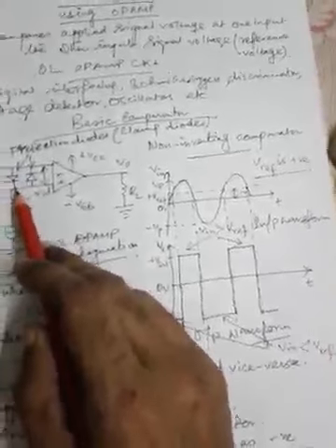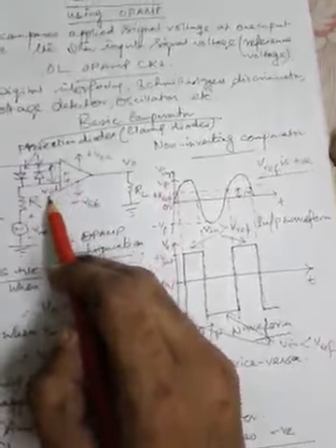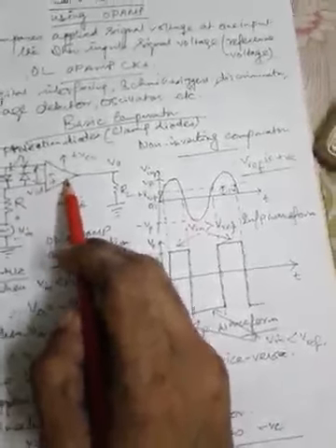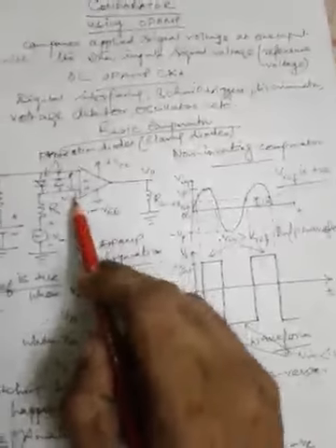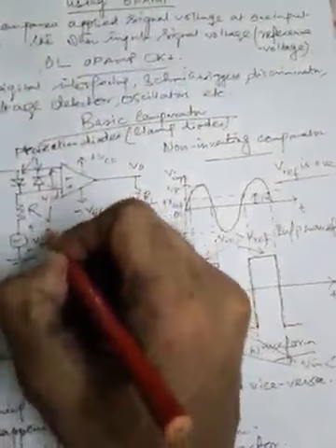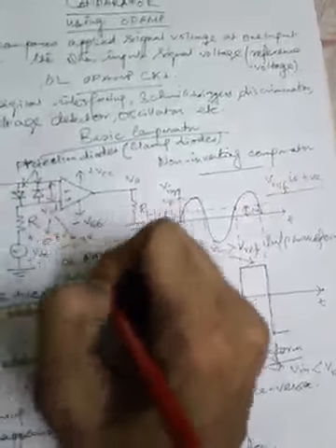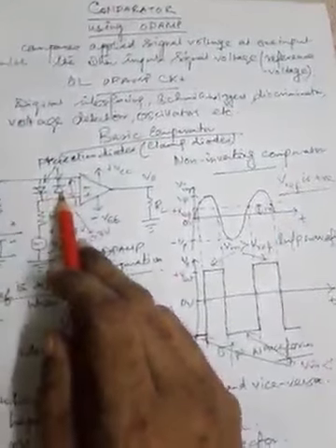through it, because since it is forward biased, it will be conducting heavily, and therefore it will not allow any current to move because of that excessive voltage VID into the op-amp, and thereby the op-amp will be protected. So whichever case, if this VID is clamped to two values, 0.7 volt or minus 0.7 volt, either one of these two anti-parallel diodes will take up the challenge to pass the excessive current due to excessive change of input voltage Vin through it, and thereby the op-amp will be protected and will not be damaged. And that's why these two diodes are called protection diodes or clamp diodes.